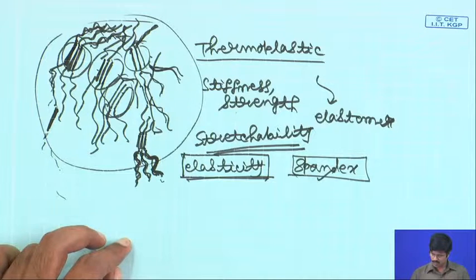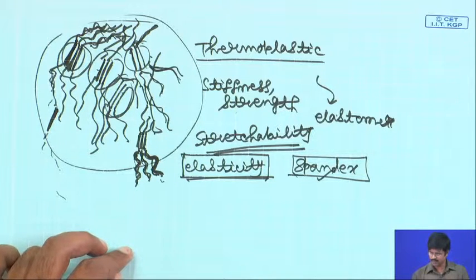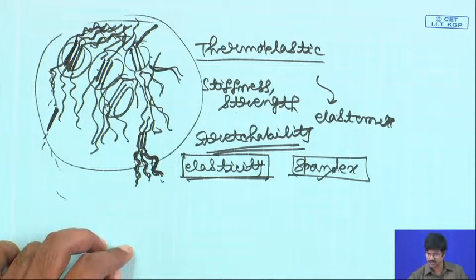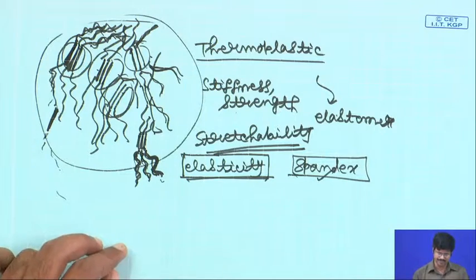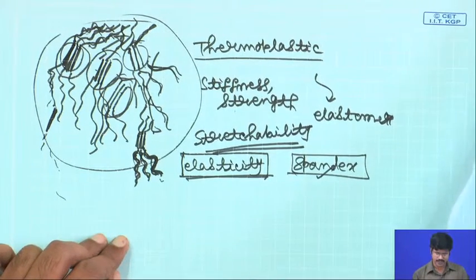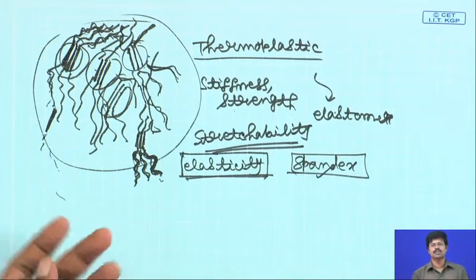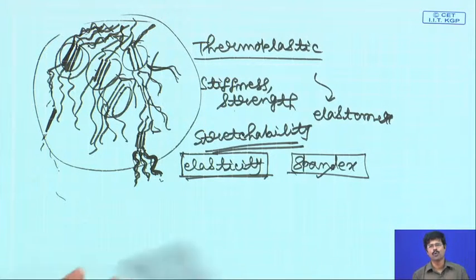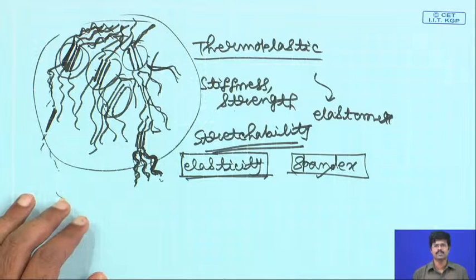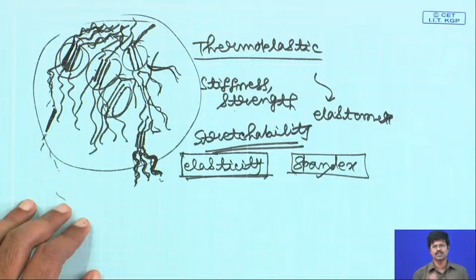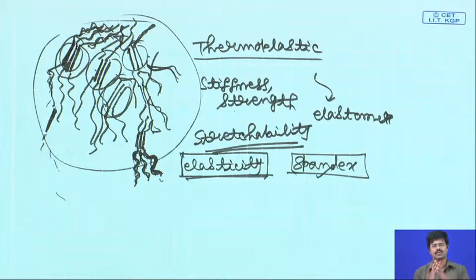All right. So, I think that is more or less all that I wanted to talk about polyurethanes, but one of the other uses also is as foams, because what can happen with those materials is that carbon dioxide can evolve when you break these urethane linkages, and if you suitably process the material, this carbon dioxide can create a lot of volume inside the material, and then you can have what you call foamy material.